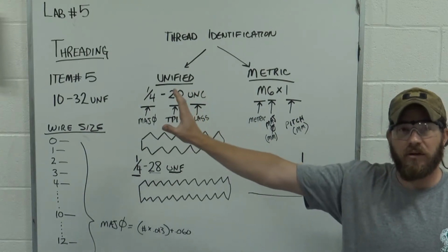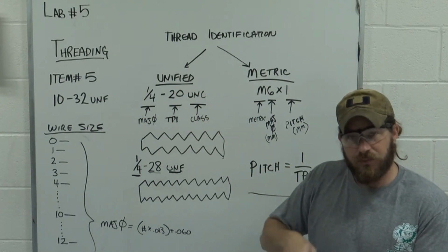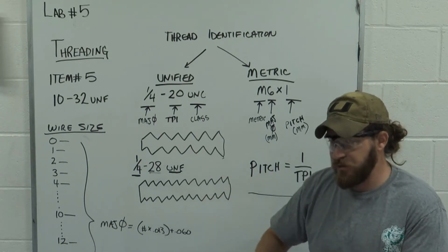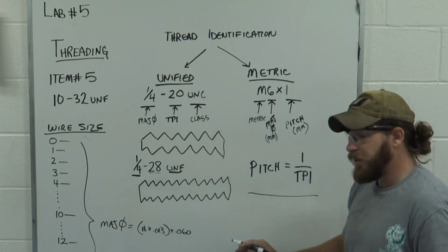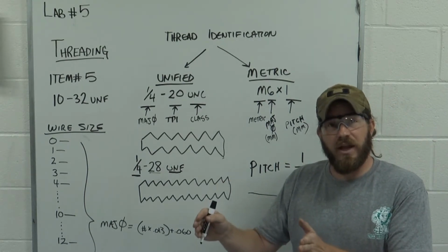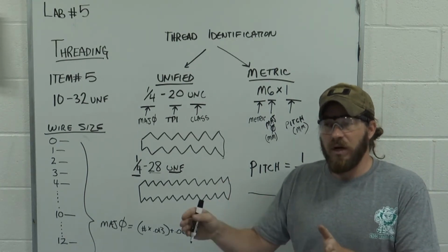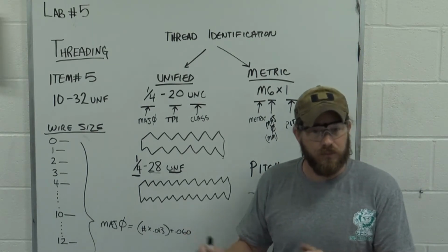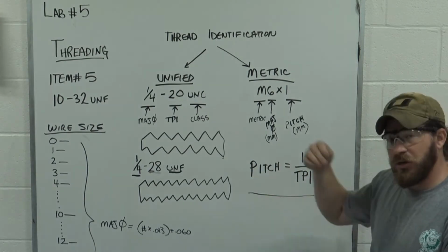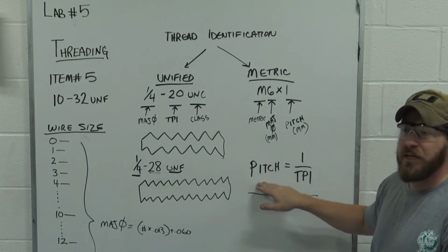Like when we're out at the lathe and we turn the handle, and it's 100 thousandths per revolution, that means that the pitch of that thread that was ground was 100 thousandths. So each turn of the dial is equal to a pitch.